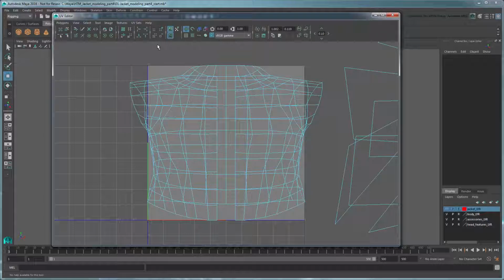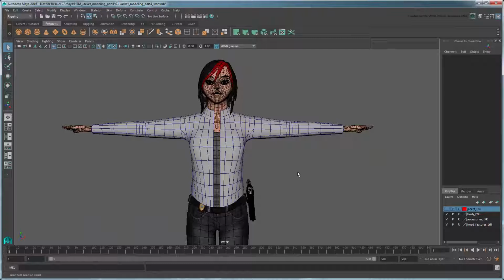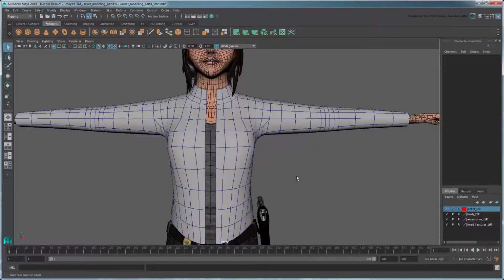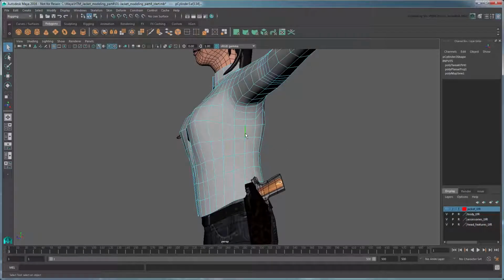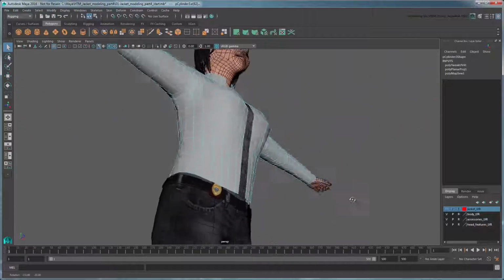As we demonstrated in our Unfolding a UV Mesh tutorial series, we next need to unfold the UV map so it can lie flat to ease the texturing process afterward. To unfold the UVs of a mesh like this, we need to cut a few seams first, just like a tailor would in order to lay down his garment flat on his workbench. Select these edge loops running along both sides of the torso. These will form our seam.